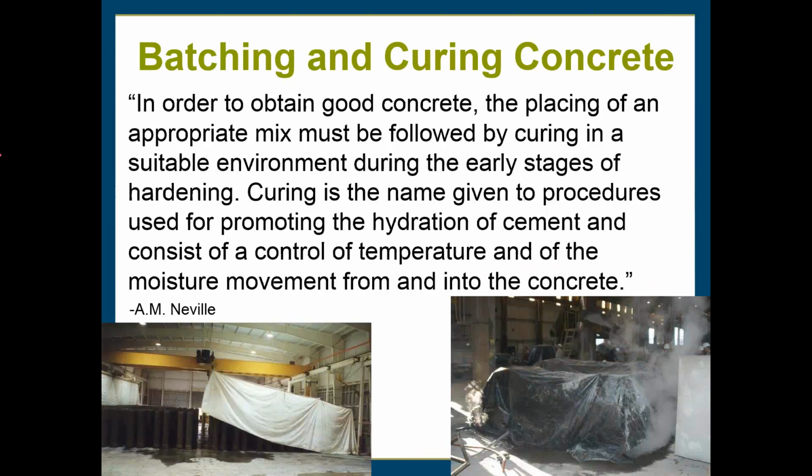So the next two slides are just some notable quotes that I found. In order to obtain good concrete, the placing of an appropriate mix must be followed by curing in a suitable environment during the early stages of hardening. So again, your mix design itself is important, but what you do with it after you place it is also very important. It can very negatively or very positively affect the ultimate strength of your product.